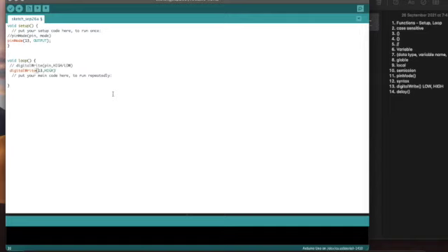Once it turns on, we want it to blink. So we will just give a pause or a delay. Once it turns on, we will give a pause of 1000 milliseconds. It can be either 1000 or 2000. It is up to us. After this, once it glows, we want to turn it off.